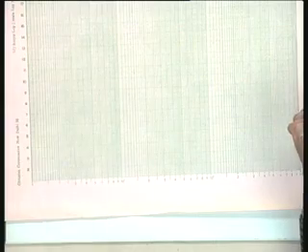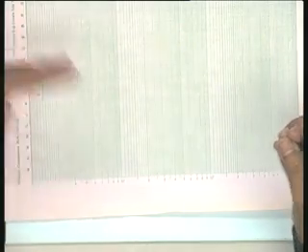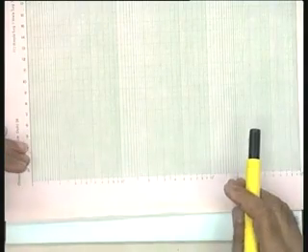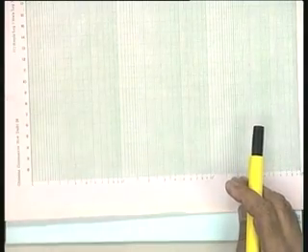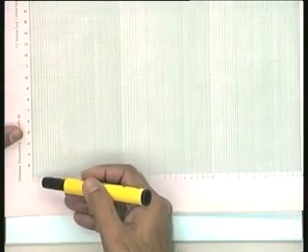Since the phase plot cannot appropriately be fitted into the format of a log paper, it is most convenient, as far as the Bode plot study is concerned, that we take a semi log paper wherein the vertical axis is the linear scale and the horizontal axis is the logarithmic scale.